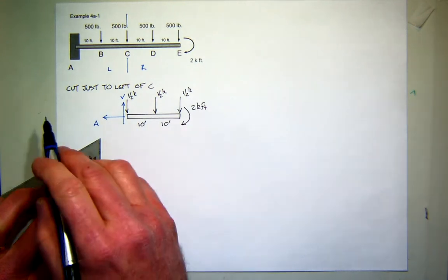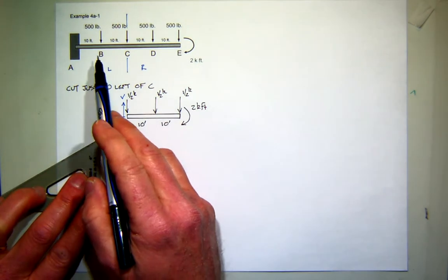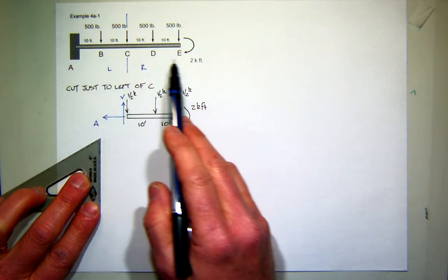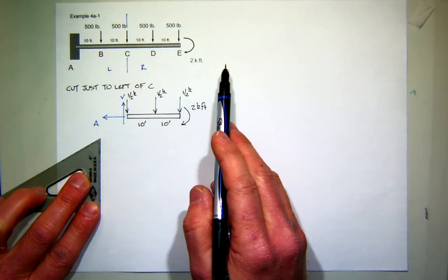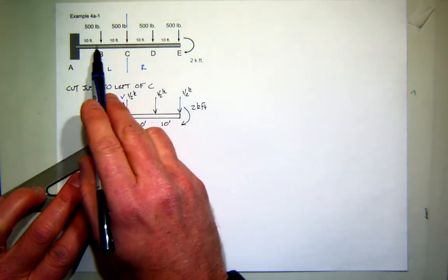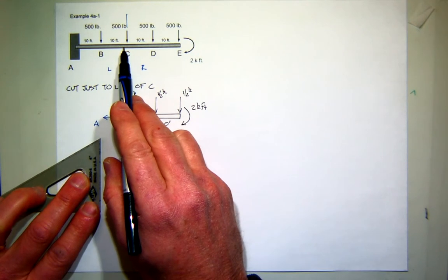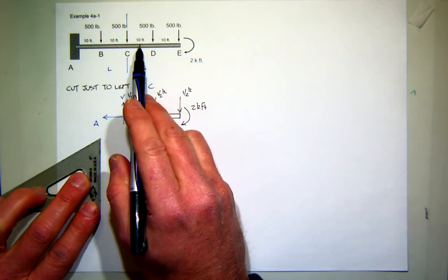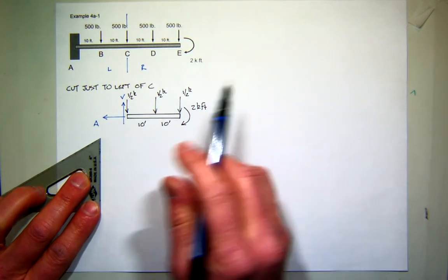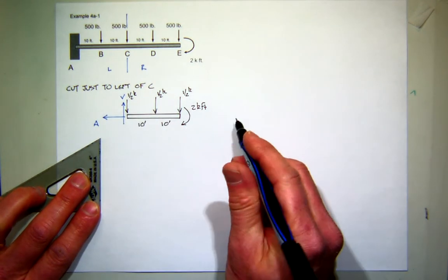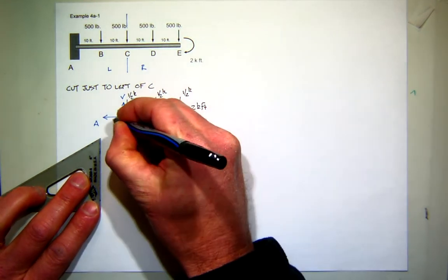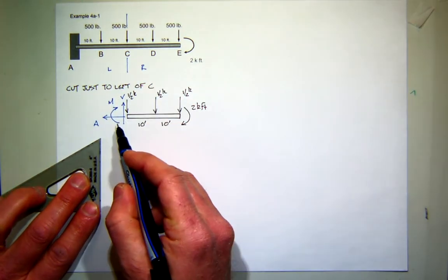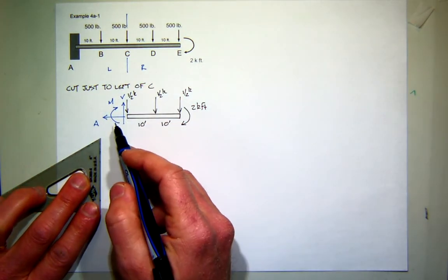Usually when you look at the variation of shear force and bending moment along the beam, you start at the left side and move to the right, the conventional X dimension. So I'm coming up to that force. I'm going to stop just before it, and then do it again just after it, and we're going to see what changes as I pass by a force. I'm going to finish this by assuming a positive sign convention for my moment.